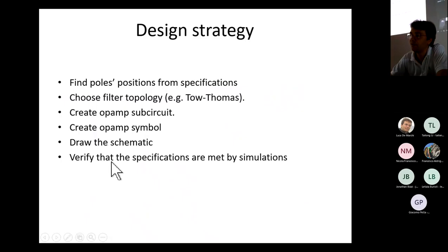Then you draw the schematic, and finally you verify by simulation that the specifications are met. To verify this, you simply have to run a .ac analysis, because we are interested in seeing the frequency response. Just a minor variation is the necessity to also simulate the variation of capacitor and resistor parameters with respect to nominal values. We will see how to run these Monte Carlo simulations.